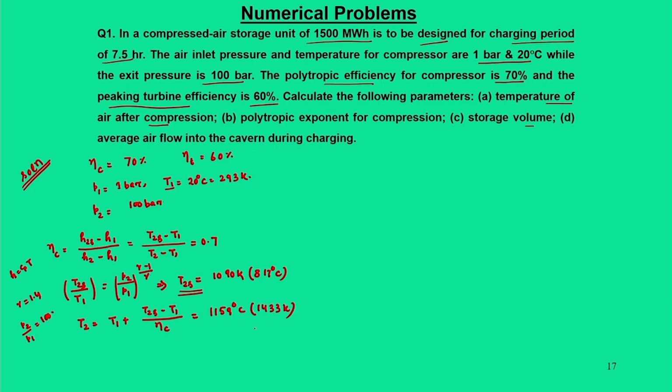But when you calculate this T2, this is based on the isentropic temperature after compression, by assuming this number, but what polytropic efficiency it would be.